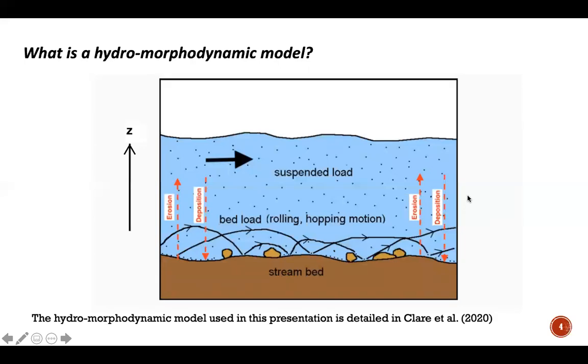And then you've got two different types of sediment transport. The first one that I'll speak about is suspended sediment transport. As the flow passes over the bed, if the velocity is high enough, you get erosion. Then the sediment is uplifted into the flow, suspended in the flow, passes along, and then as the velocity slows down somewhere else, it gets deposited.